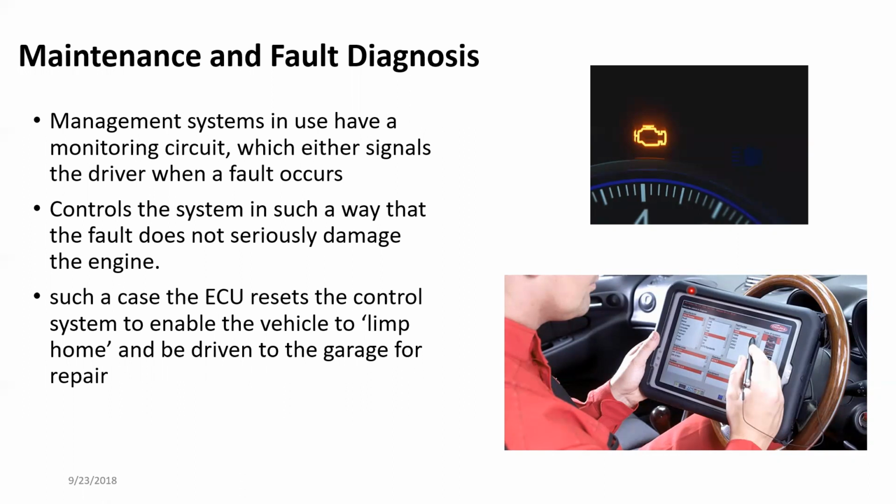That 300 RPM could be wrong, because for throttle positioning and any other engine loads, there's a corresponding value. So that means something is wrong with the engine RPM reading. So check the engine RPM reading, something is wrong. That's what the code says.